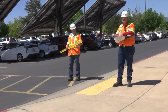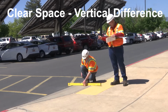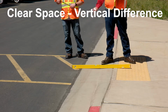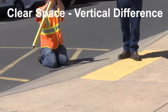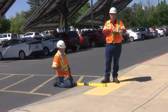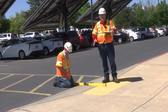And lastly, on the clear space, we check to see the vertical discontinuities. The most common place you'll see a vertical discontinuity in your clear space is at the start, where you transition from your top back curb to your gutter, or from where the gutter meets the asphalt. We have a small lip between the top back curb and the gutter at 3/8 of an inch. That 3/8 of an inch falls within that 1/4 of an inch to 1/2 inch, so we need to have a surface that is beveled at 2 to 1. And looking here, our surface is beveled at 2 to 1, so we're okay.